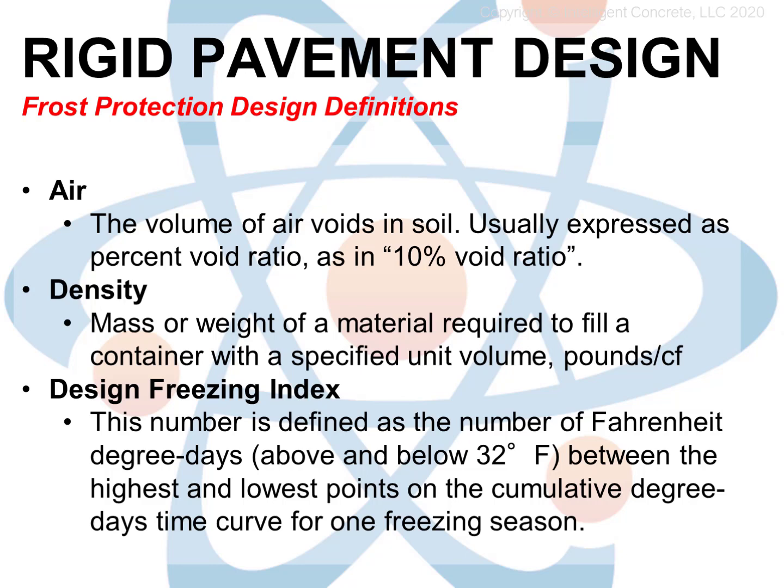Think of cake, angel food and fruit cake. You can compress angel food easily between your fingers because it's mostly air. You could use a loaf of fruit cake to hold up your car while changing its tire because it's so dense. Uncompacted soil can have a void ratio that can exceed 100%, meaning half the volume of the soil is air. This void space can also be filled with water. It's the water within the void spaces that causes the problems under freezing conditions.